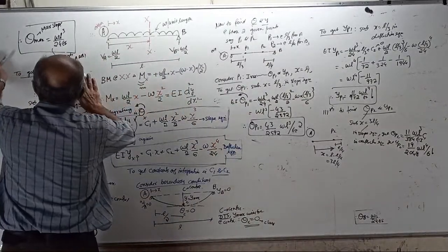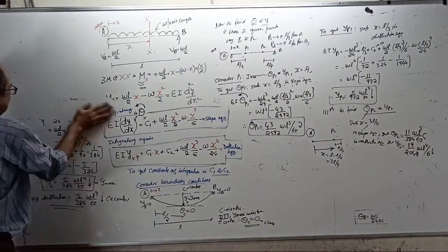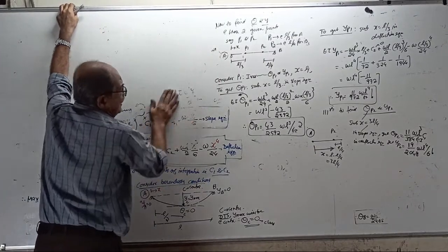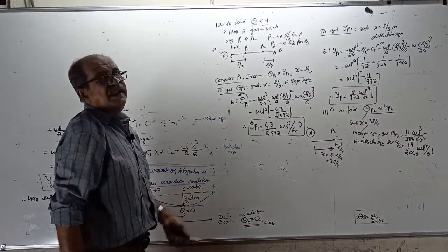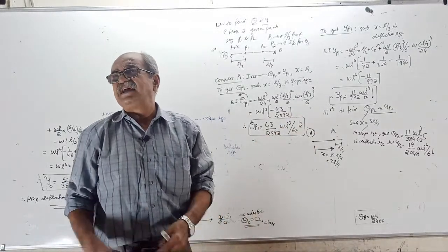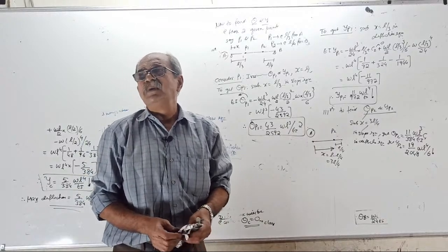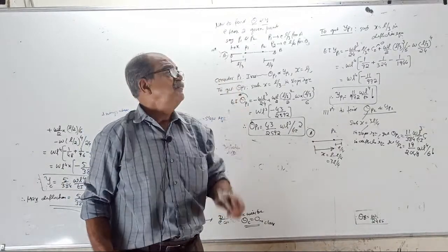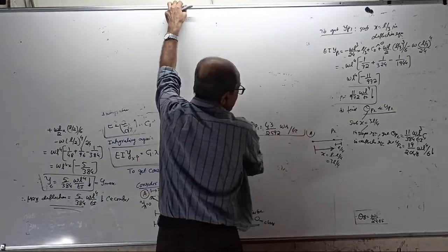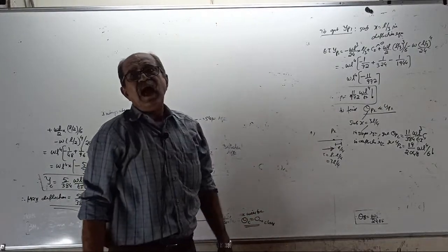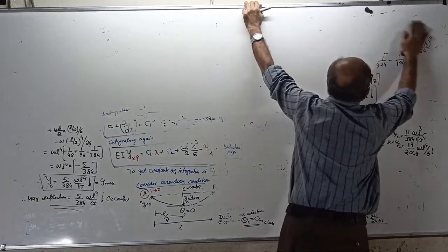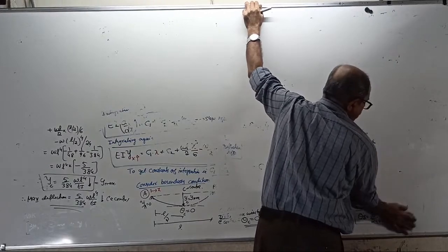I will go to the next question. I will rub the full board. Now remember, you will understand why. If the full span is UDL, between the two ends there is only one section, between the two supports. Wherever you take a section, in terms of x, Mx will come the same. It will have a single variation. Means there is no change in between. That's why, if the full span is UDL, the double integration method and Macaulay's method are both the same. Later, for Macaulay's method, I will not do full span UDL. Why? It is the same, no change.